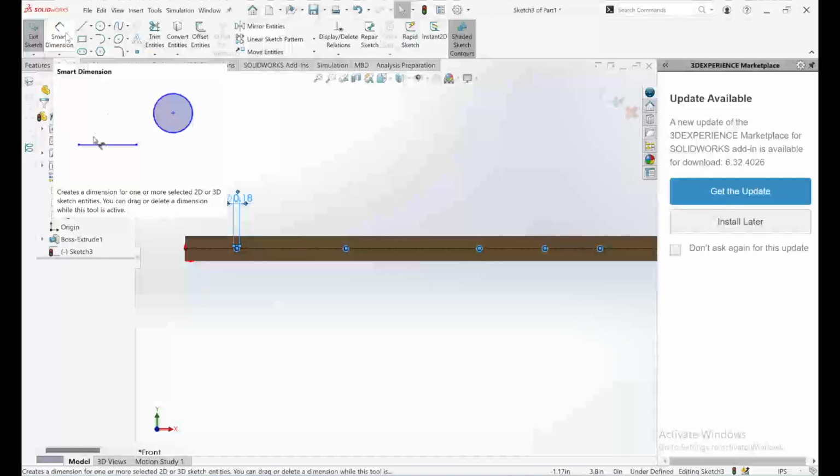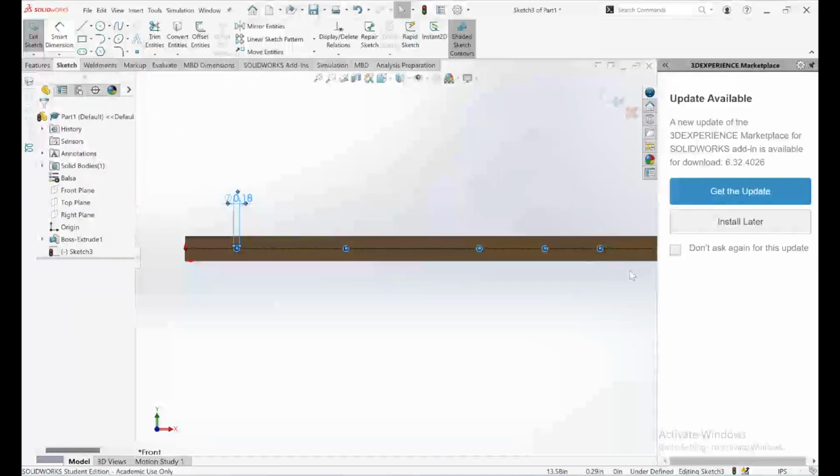When you're designing your beam, you set this probably to be 18 inches long, which is correct because you can only have your main beam to be a maximum of 18 inches. And this hole cannot be right on the edge. So if you designed, let's say, your bridge to have a member going up right here, it cannot connect right at 18 inches because it will be right on the edge and your screw will not be able to hold anything.